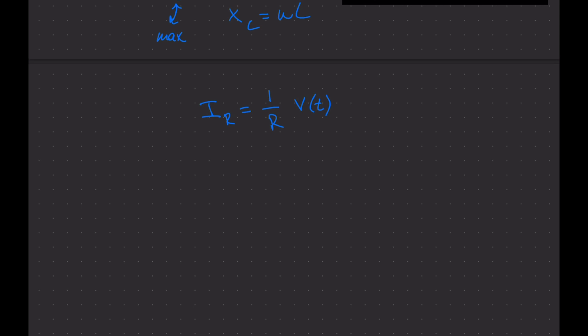What we saw on the inductor was the voltage as a function of time is equal to negative L di dt. So the current is actually buried inside this time derivative, and the voltage depends on the change in the current. That's why it responds a little differently than the resistor.